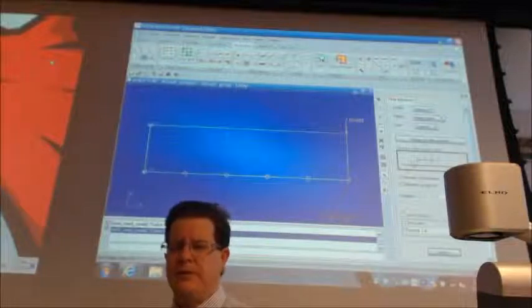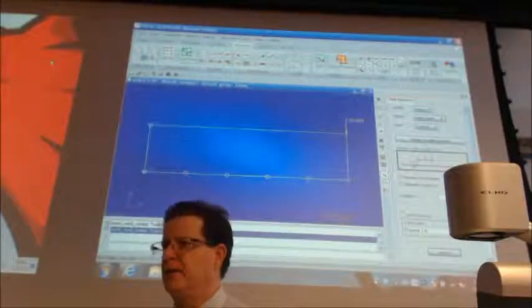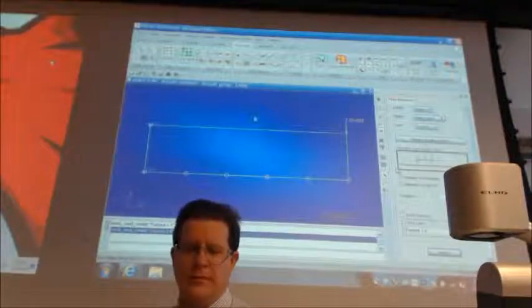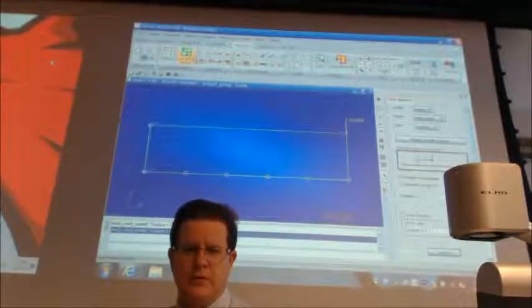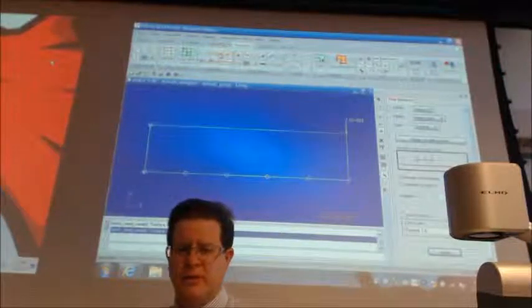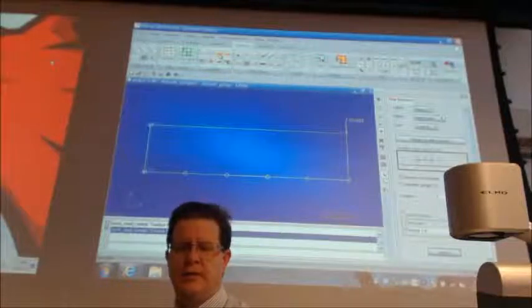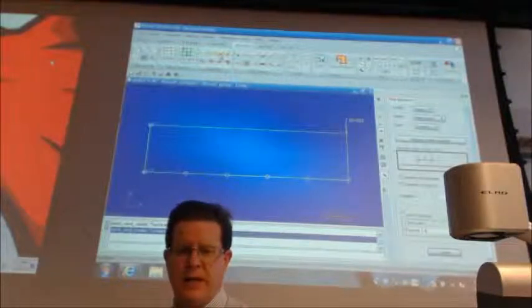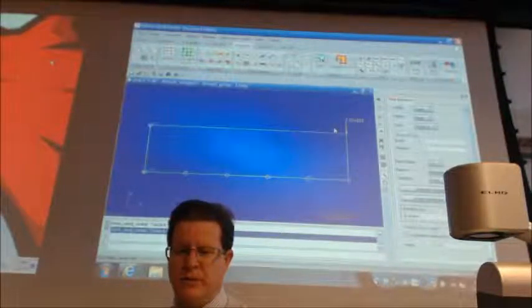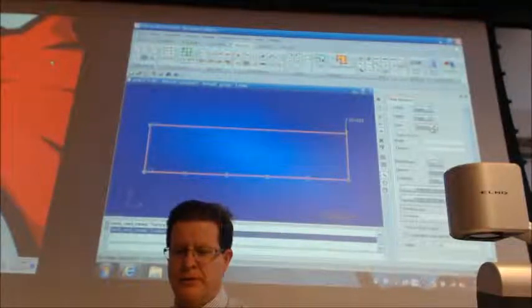Prior to what we've been doing today, our elements have been 1D, one-dimensional. So let's see. So now we want to put a mesh on this. So we go to meshing and we pick surface. So remember, the mesh seeds are just telling Patran where to put the nodes. Okay, so we want to create a mesh on a surface.